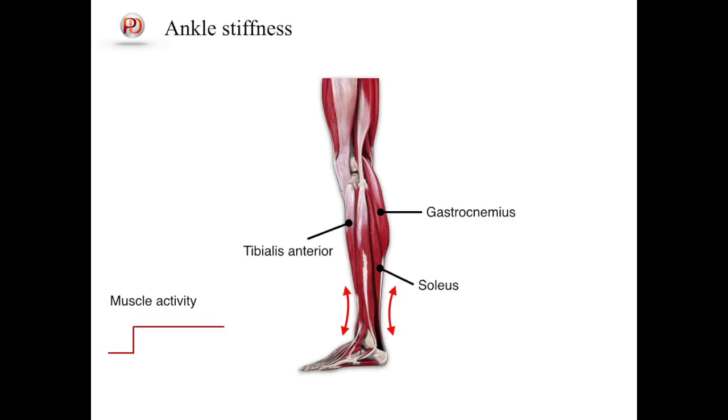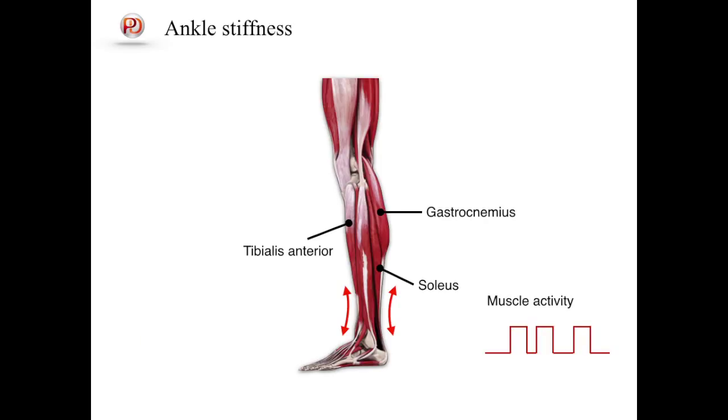For a long time, it was thought that upright quiet standing is stabilized by the high joint stiffness caused by tonus of muscles around the ankle. But recently, a new control hypothesis was proposed, in which the brain plays a more important role. The control signal from the brain switches the on-off of muscle activity. Hence, the upright posture is no longer asymptotically stable, but the state point is controlled to be near the upright posture. We will examine both control strategies by simulations in this tutorial series.